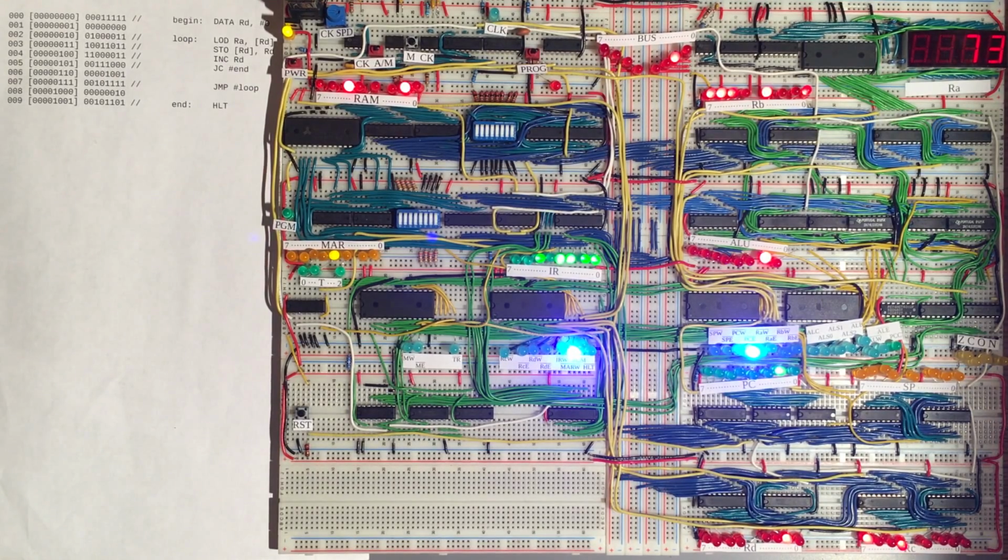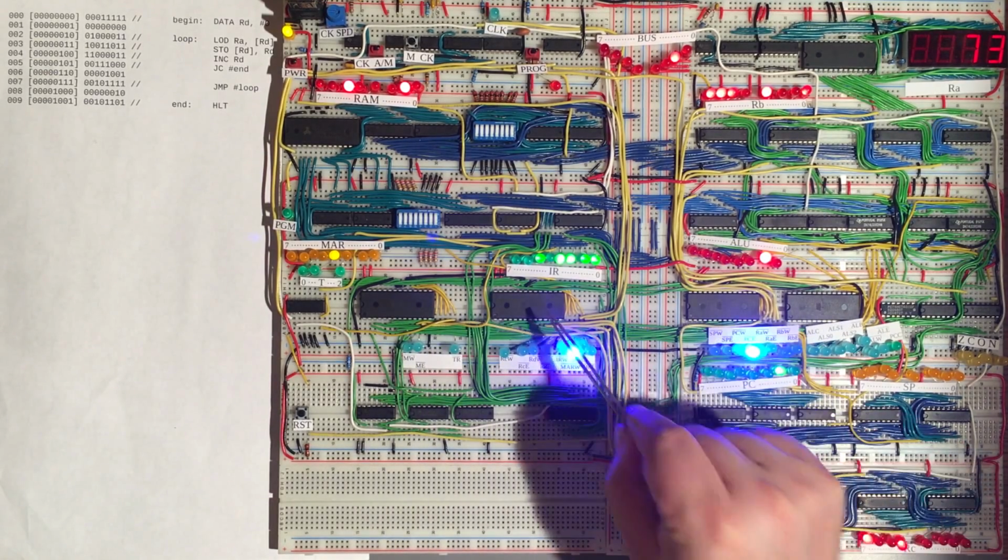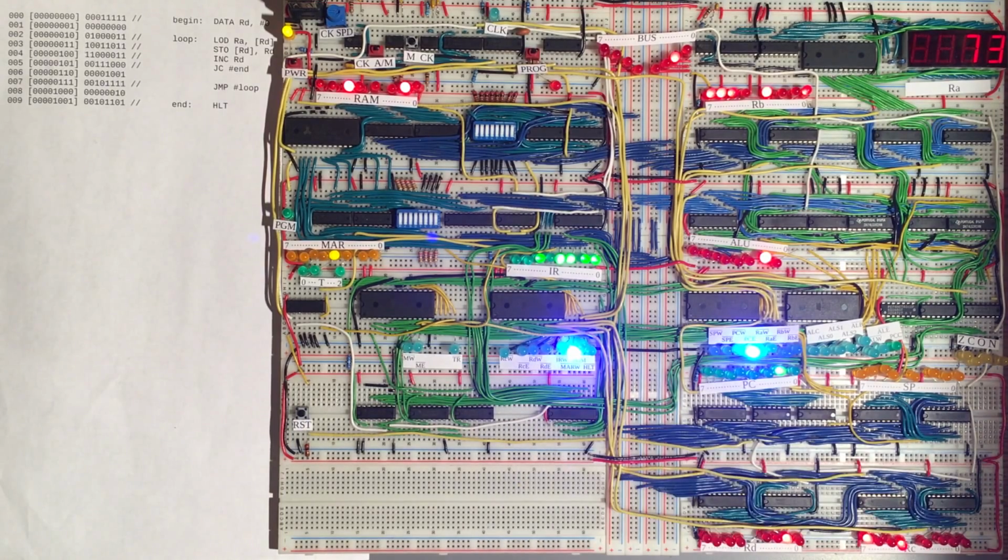And so today we're going to finish looking at the microcode, which is programmed into these EEPROM chips here, which make up the control unit of this CPU. And so in the last episode we started looking at that microcode and we looked in detail first at the microcode for the various move class instructions that our CPU supports.